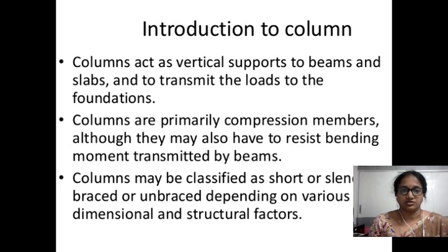It acts as a medium between the loads coming from the top and transferring to the soil. Columns act as vertical supports to beams and slabs and transmit the loads to the foundation. So columns are primarily compression members, although they may have to resist the bending moments transmitted from the beam, but generally columns are known as compression members. Columns may be classified as short, slender, braced or unbraced, depending upon the various dimensional and structural factors.